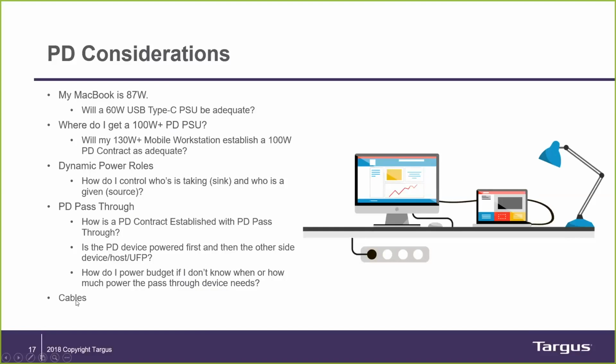And then of course, cables. Some cables aren't rated to do, we talked about that earlier, the need for a 5 amp cable when you're doing 100 watt USB Type-C power.